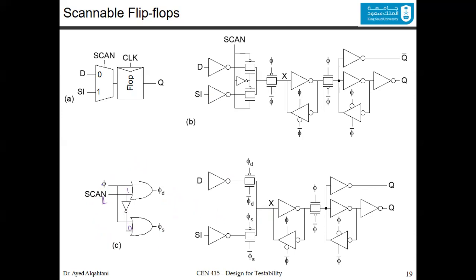If this is 1, no matter what you give to it, here phi, that result will be 1. So you are not clocking, it's static 1. Here, since it is 0, the phi will go to the phi of S and the clocking will happen here, and the serial input will go inside the flip-flops, or you will be in the scan.